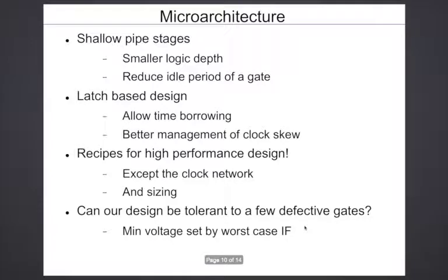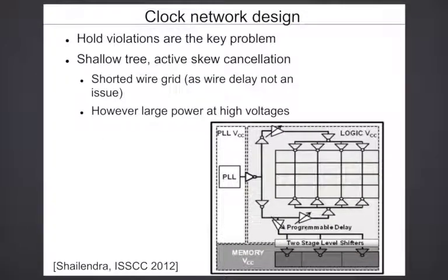You can have the delay synthesizer of... Correct. So the suggestion is, why not also use a delay synthesizer? Now the thing with the delay synthesizer of the paper from Nakai is that the synthesizer was essentially a bunch of logic gates, a bunch of wire segments, and then a mux to select between the two.